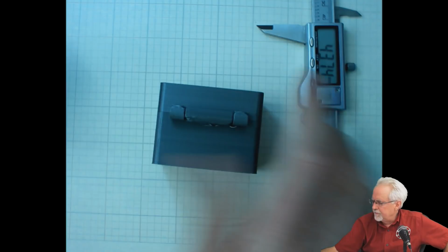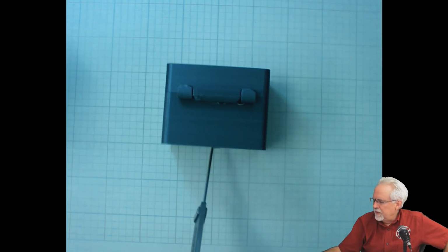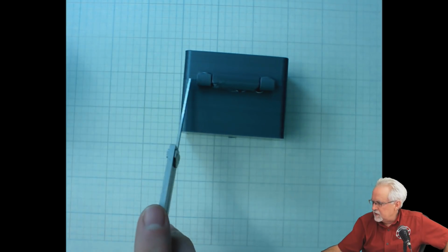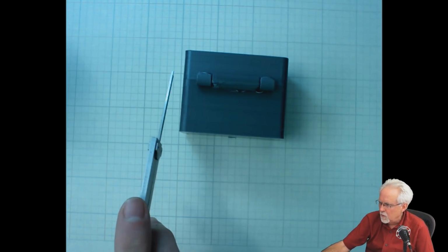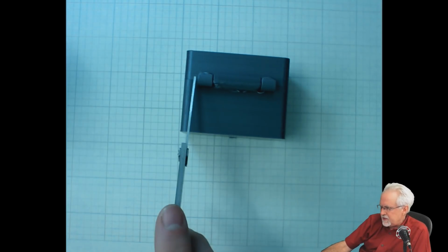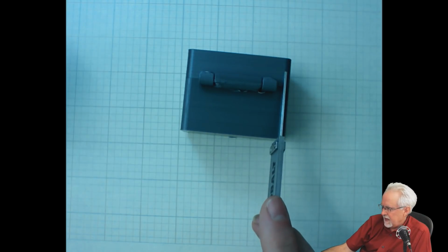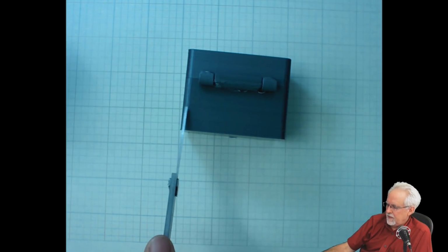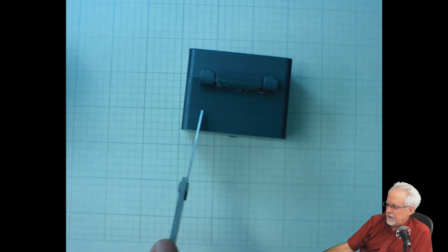What is another parameter? This is a very important one, and you've got to think about it, because I wouldn't want the hinge to go from here to here, because you would have this goofy spot at the round corner where the hinge is just hanging out in the middle of nowhere. Really what I want is for the hinge to go from the start of the flat part to the end of the flat part. So I'm going to need a parameter which is the flat dimension, from here to here, and that's going to depend on both the width and the amount of rounding.